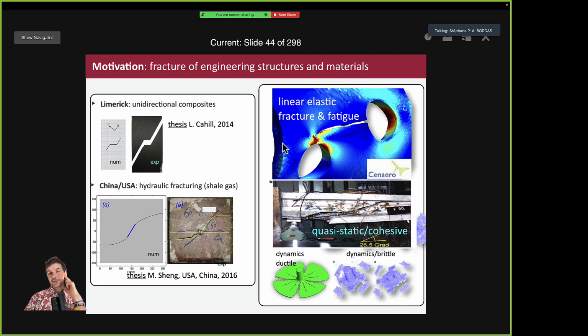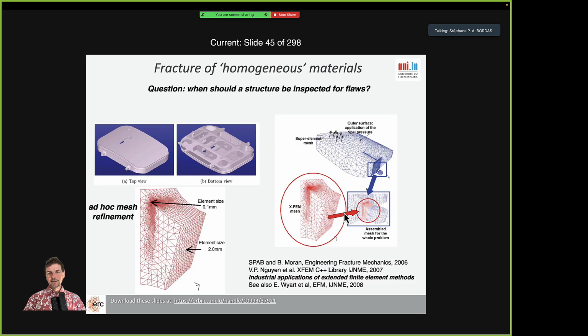And it is quite a difficult problem because the crack is 3D, so it just glazes off the interior here of the hole, but does not stop there. It continues, it deflects. And this is very hard to find if the error estimate that you have is not precise enough. And finally, we talked also about mesh-free methods for cohesive, quasi-static crack growth, and this is something which we worked on with Timon Rabczuk using element-free Galerkin with or without enrichment. So these papers are from 2007. They are highly cited now, and you can take a look at them if you're interested.